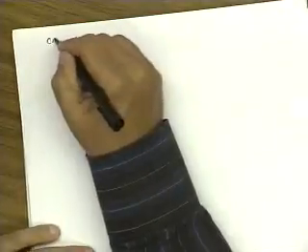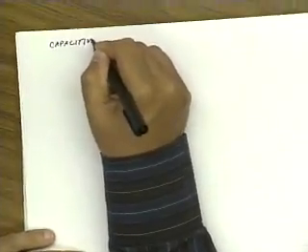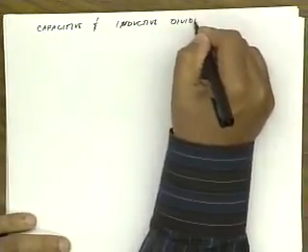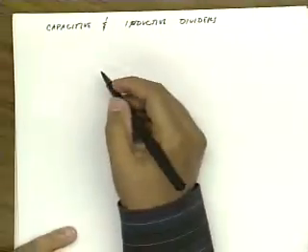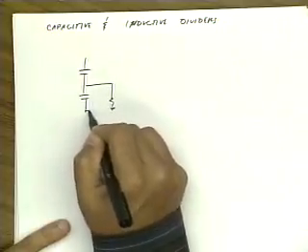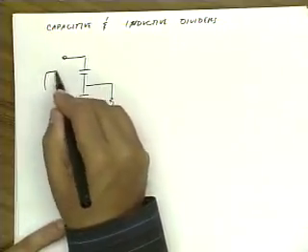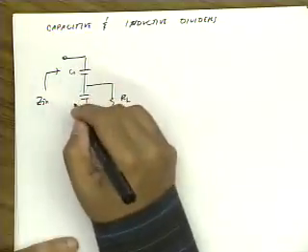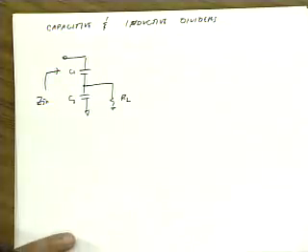All right, so how do we build impedance matching networks? So the simplest impedance matching networks are capacitive and inductive dividers. And the idea is, let's say this is RL. What's the input impedance looking into this network? Well, this is a very simple circuit. Let's say this is C1, C2. We could analyze it completely and come out with an expression, but let's just come out with an approximate expression.